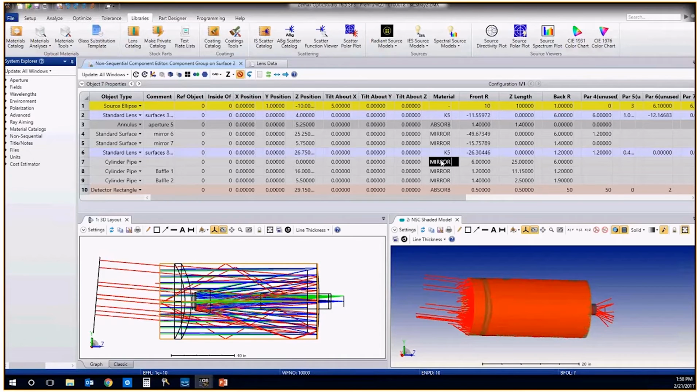Basically what happens is if you have a mirror material and no other coating, when you go to apply the scatter function, if it doesn't have its own energy allocations as to how much energy is reflected versus how much should be absorbed, then we're going to fall back on the idea of a mirror coated with aluminum. So it won't have necessarily 100% reflectance.